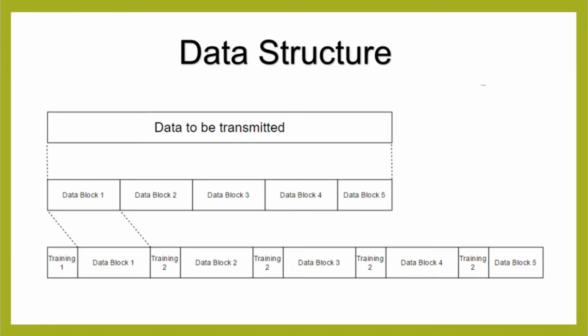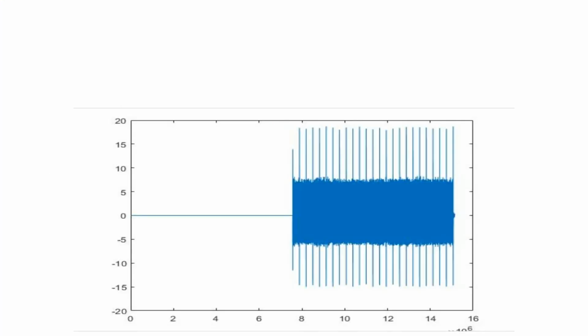To help the receiver find out when the transmission of the file begins, every transmission starts with a special training sequence which is already known to the receiver. In PPM, it is very important to keep track of the pulse train. As an additional safety measure, several smaller training sequences are used in between to divide the file into several packages, which helps keep the receiver synchronized during the whole transmission.